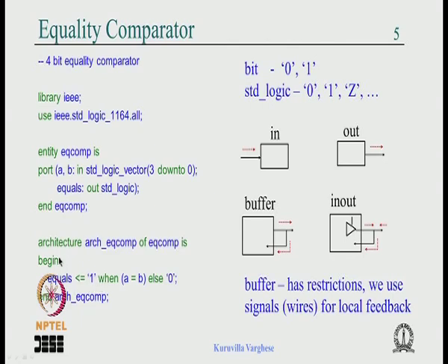Before the begin, you could declare many things: you could declare components, you can define functions, procedures and so on. We will see what could be done there, and what the statements are. Say this is an output signal and this is an assignment operator, which is exactly similar to less than or equal to. VHDL also uses the same for less than or equal to, so depending on the context the meaning is derived.